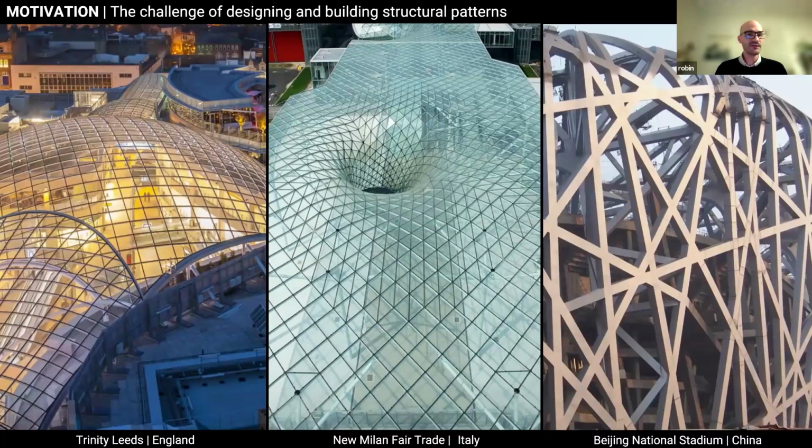In the middle, you can see that funnel where you have a transition between the horizontal part and the vertical part. And you can see that the two areas where you have this complex transition have been patched between regular quads, like here at the bottom, a triangulation here, and then a gradual transition.